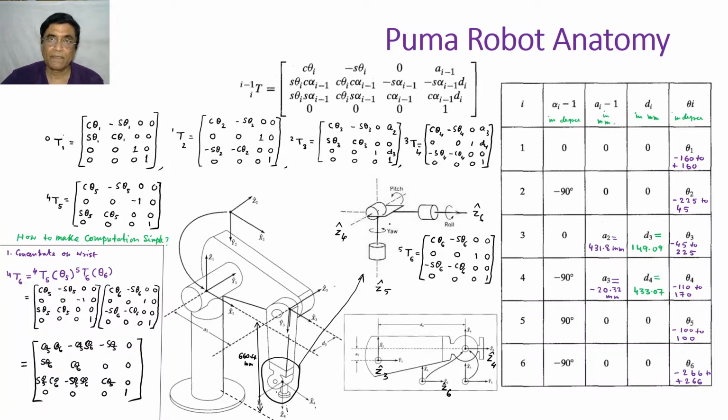They are giving yaw, roll, and pitch motion to the PUMA wrist. So there are 3 degrees of freedom here, 1 degree of freedom in the elbow, another on the shoulder, another on the base.